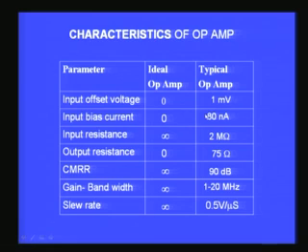So, in actual case you would find it will be around few nanoamperes. In this case, in a 741 it is 80 nanoamperes. Incidentally, you can also buy special purpose operational amplifiers which can have this input bias current a very low value of the order of picoamperes or even femtoamperes. Picoamperes corresponds to 10 power minus 12 of an ampere, or femtoamperes 10 power minus 15 ampere.